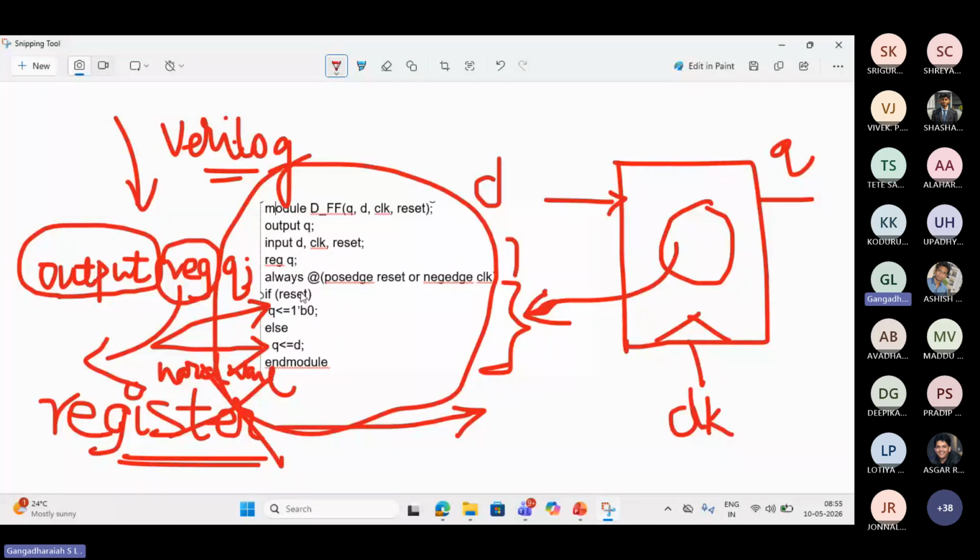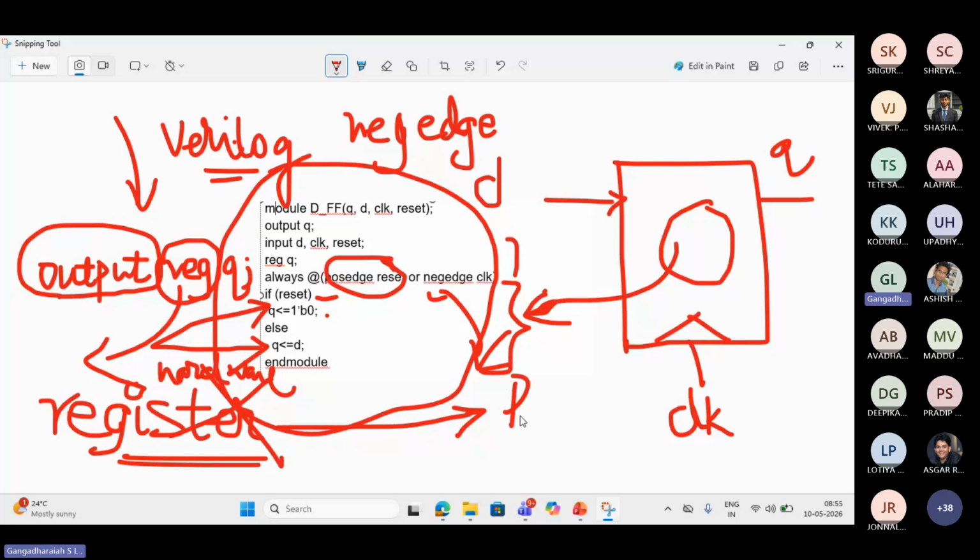Let's say if reset is 1, my Q is 0 because it is my positive-level reset. But generally the industry assumption is reset should always be negative. You can negate, because this is taken from some reference. That's why I've used it in books. You will see these kinds of definitions, of course, but it is opposite. Clock is always positive edge because I need to give you some reference with respect to the book. So clock must always be positive in general, of course, but logically I don't see any difference. Negative also works.